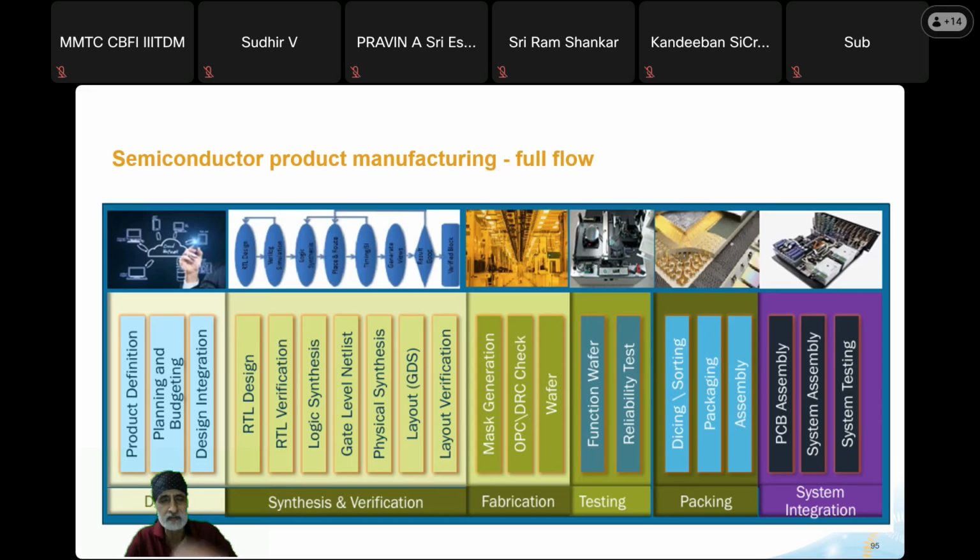The format GDS will contain certain information. Based on that information, the mask fab will prepare masks, and those masks are used in the fabrication of the device. Depending on the technology, there can be 21, 22 masks, or it can be around 50, 54 or 55. One mask normally takes 1.5 days. So if there is a product which has 30 mask sets, it will take 45 or 50 days for the complete fabrication.